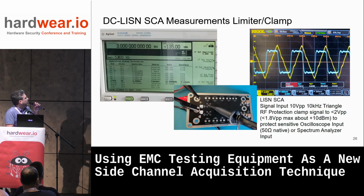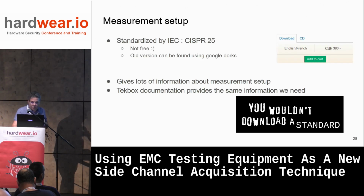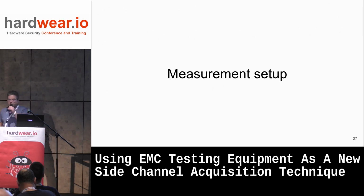And then here it's a check of the limiter clamp, which is a very important point to avoid burning your oscilloscope input or spectrum analyzer, like we see there. I put in a signal of 10 volt peak, and there it limits the signal at the output, which is there, to less than 2 volt peak, so about 10 dBm. So let's see the measurement setup.